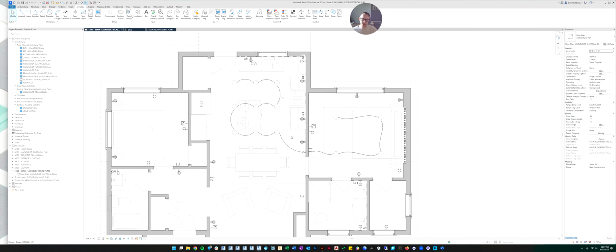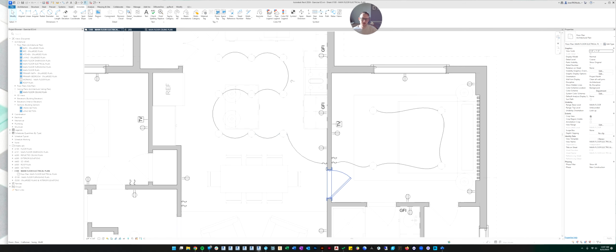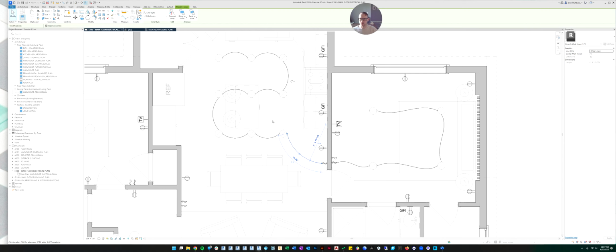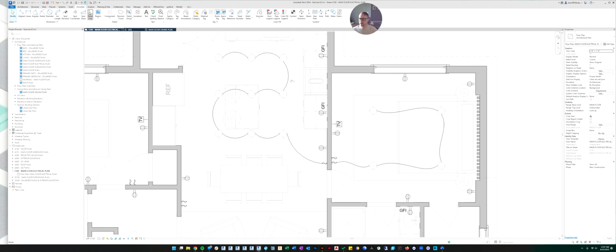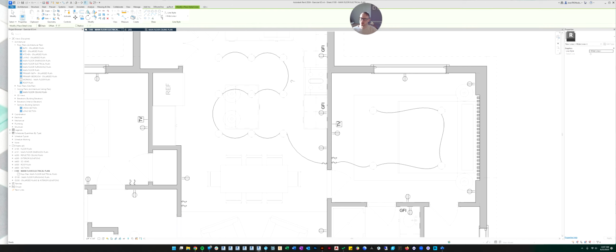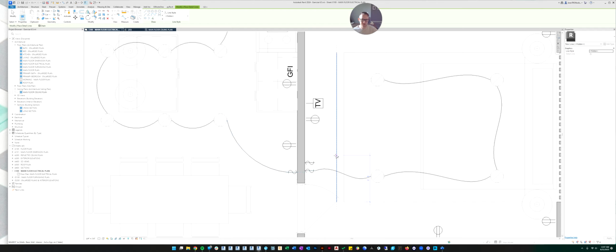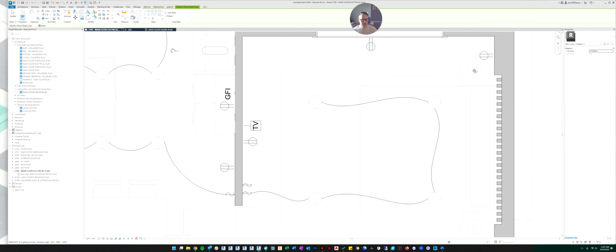So the other thing I like to do with my lines is I don't like the wires to be solid. I want them to be dotted. So we've been using the wrong line type. When you go into detail lines, there's the tools that you can use, and you can also pick the line that you want to draw. So if you would just pick hidden line from the beginning, then you can draw, let's hook up our pendant lights. So let's start here, and let's draw a line over to the pendant.